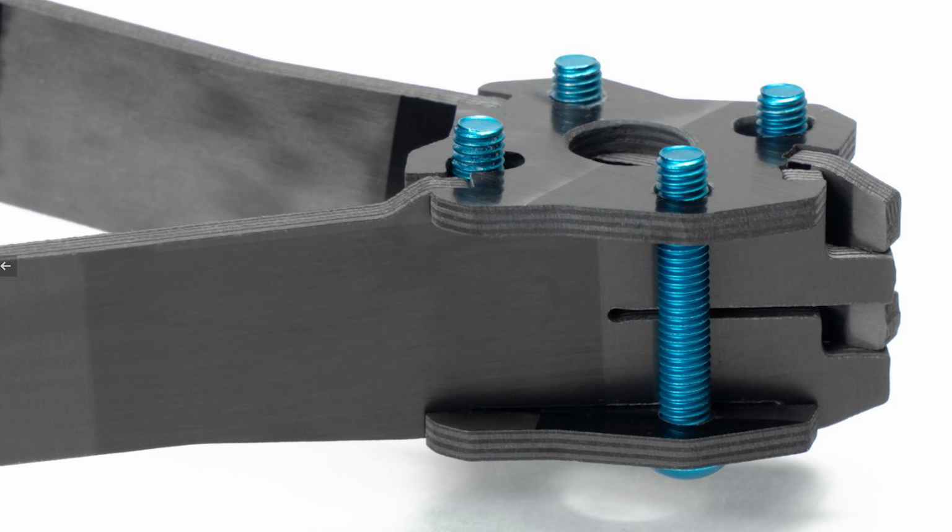Yeah, something like that. You still have a radius, but it's very small. A normal water jet machine has a nozzle of around 0.8 millimeter. We are using a so-called micro water jet machine. They're extremely rare. So we are cutting with a nozzle that is 0.3 millimeter, so our radius is 0.15 millimeter. It's so small that you can hardly see it. It's perfect. And the cool thing is you can run it extremely fast. It's faster than anything else.